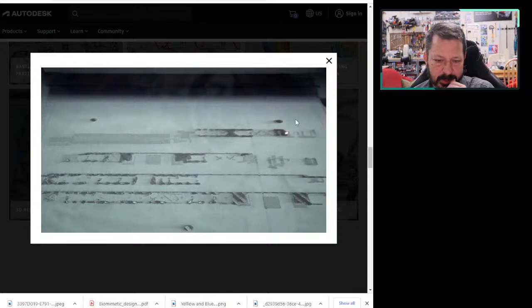So the way these laser printers work, all this grayish white stuff is powdered metal. They have their own special blend of metal that's specific for airframes at Airbus. So whatever their alloy is, it's ground into super tiny little particles and laid out on a surface. And then the laser goes around and heats up those particles to their melting point so that it fuses them together. And then another super thin layer of powder is deposited over the top. It's kind of like a wiper that wipes a new layer of powder across it, and then the laser comes back and welds another layer on top. So it's built up layer by layer still.